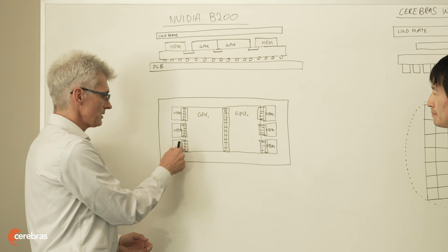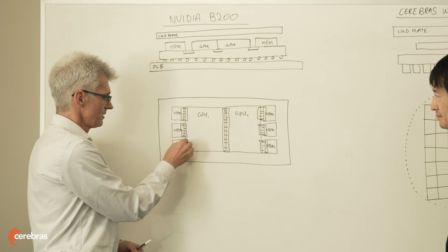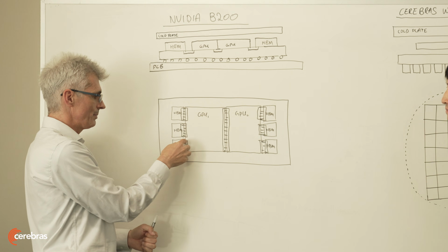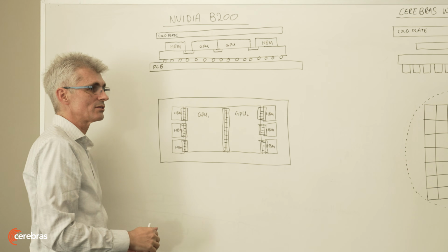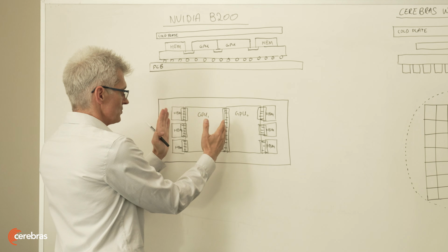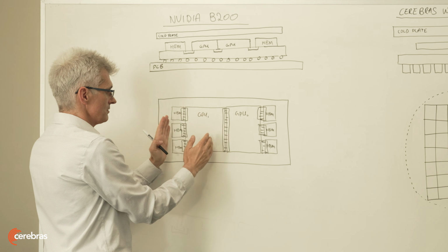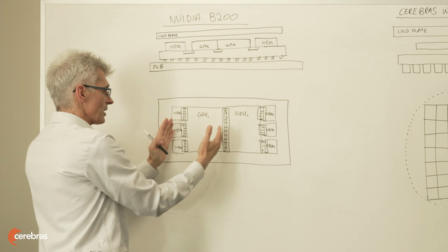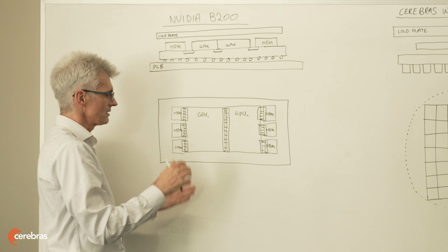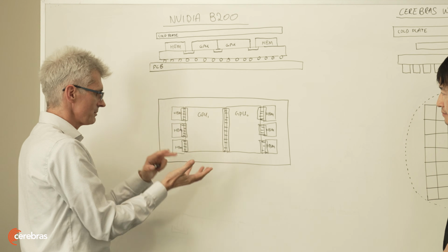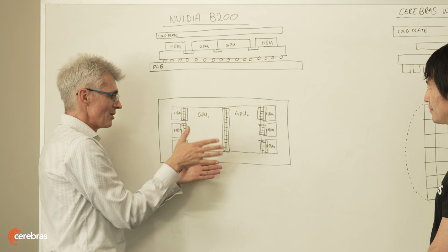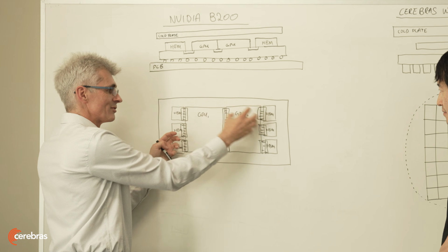Well, you need to align these very, very carefully so that they can match with the pins that are on the bottom of these die and on the bottom of these memories. You can imagine that when you want to align these bridges, you need to either start by aligning them on the substrate and then put the die on top. That's one technique. I believe that's not the technique that's used here. They might be doing it backwards, where you put the die somewhere and you assemble the bridges on top of the first die.